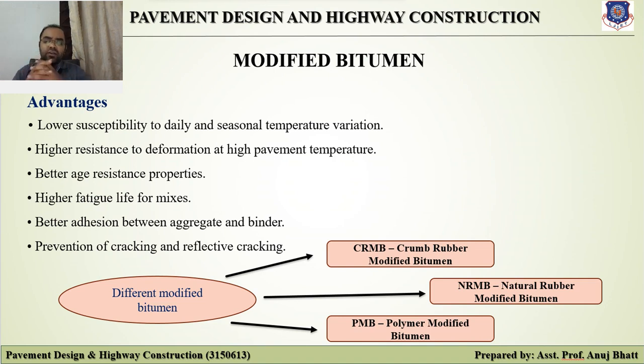Now there are a few requirements why we require this kind of modifiers, because they are very compatible with bitumen. They resist degradation of bitumen at mixing temperature. They are capable of being processed by conventional mixing and laying machinery.